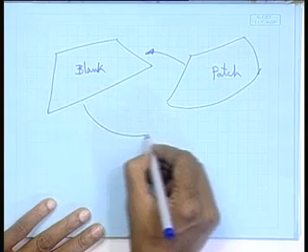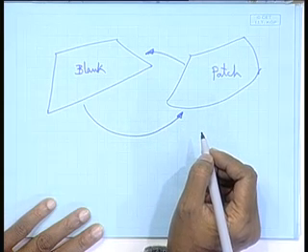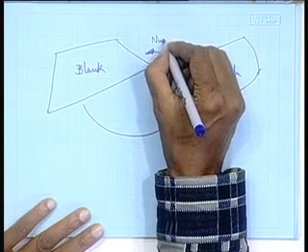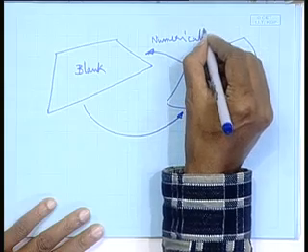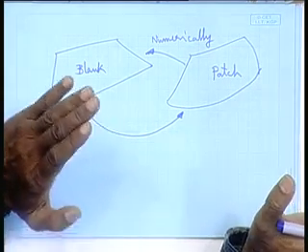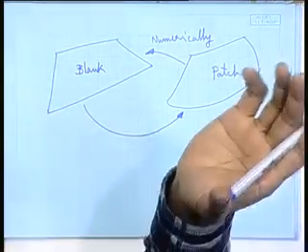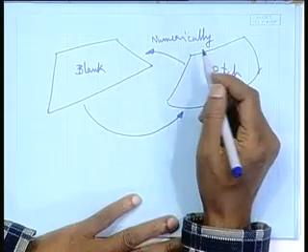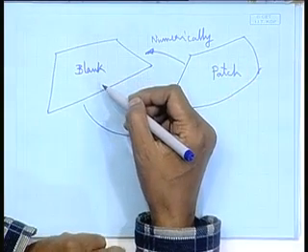Again from the blank this patch is to be generated. This has been done numerically. The patch is already generated by the hull designer, whoever has generated the hull form, he has given me this information. He has generated the hull form, he has described the welding lines. So one particular patch, suppose I will have to develop it. So I have the XYZ coordinates of this patch, and I have a numerical way of getting to the 2D shape.